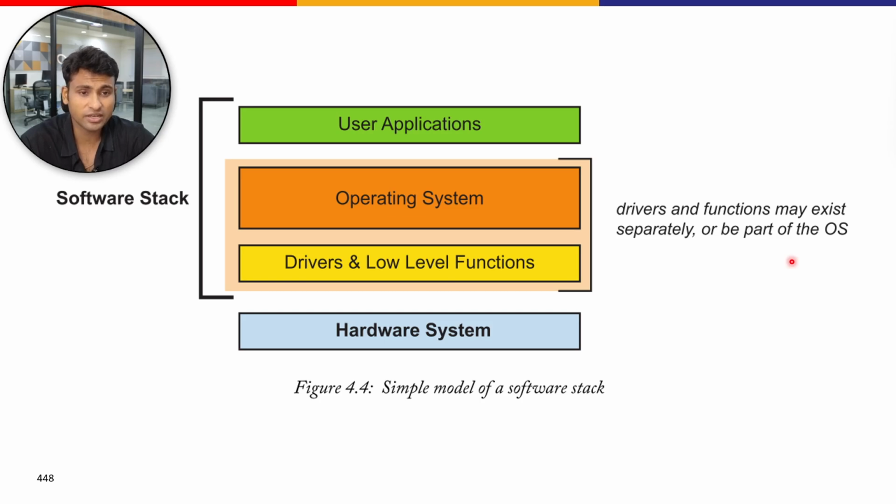In a typical scenario where the FPGA is deployed, we use both APU and RPU, and we will generally assume that two different types of operating systems are deployed: a desktop/embedded operating system like PetaLinux or Ubuntu on the APU, and a real-time operating system like FreeRTOS on the RPU. There are different possibilities which exist, ranging from using the APU or RPU in isolation with a single OS, right through to a more complex scenario where different operating systems are running on individual cores.